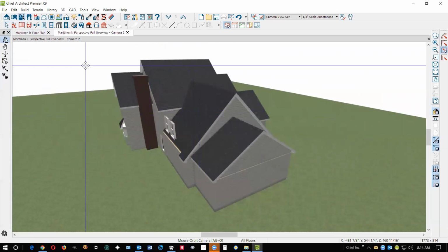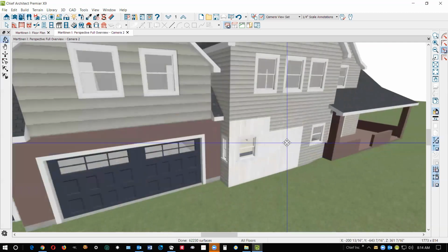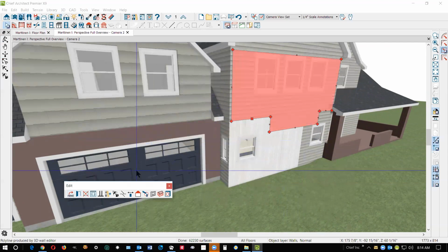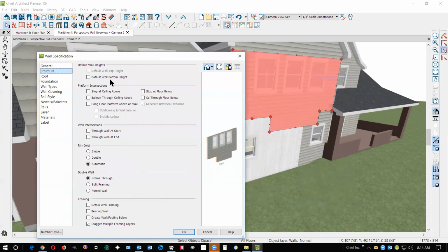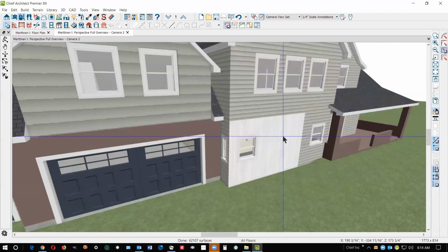Let's see where that Z siding was. Yeah, right here. And this is something that you caused also. We'll click on this and then hit the next button or tab key. And you can see the wall polyline has been altered. So I'm going to go to the structure tab and see for some reason you altered the bottom of it. So I'm going to undo that. And that should make that back into a rectangle, yeah. And then this wall here,